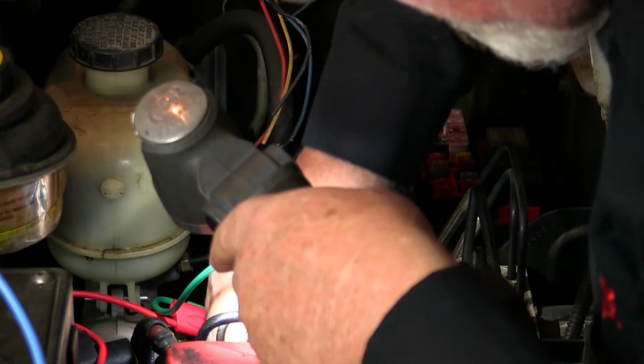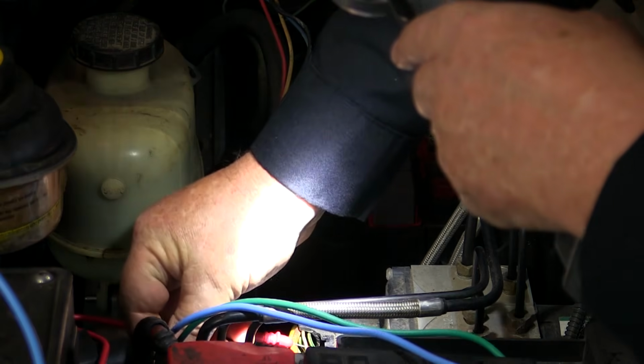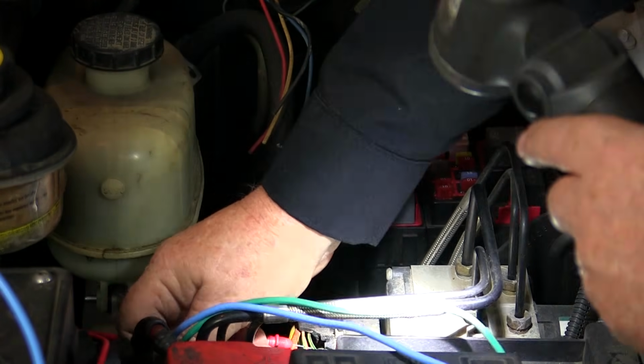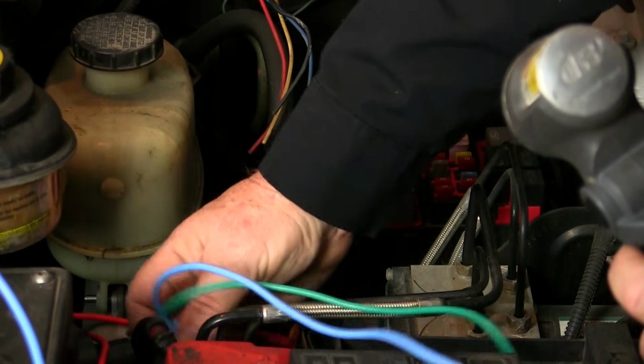Now the anti-lock brake control module is not only responsible for monitoring the speed sensor signals and sending data back and forth to the PCM and other modules on the vehicle, it's also responsible for operating the hydraulic control unit. I'm pretty sure that the 2 60 amp fuses are tied to the operation of the ABS's hydraulic control unit, so I'm not going to worry about them for now.